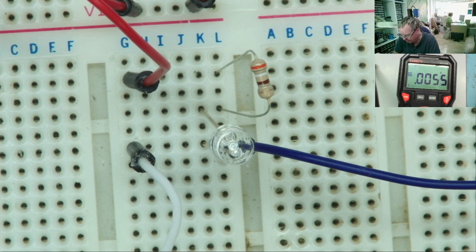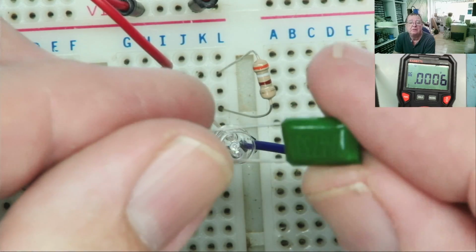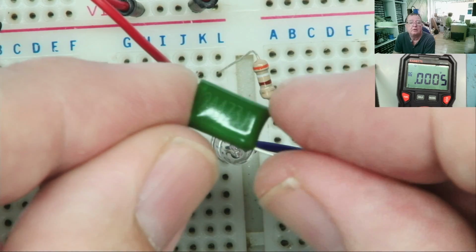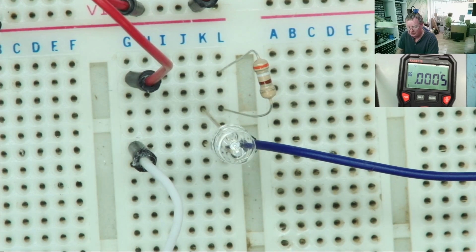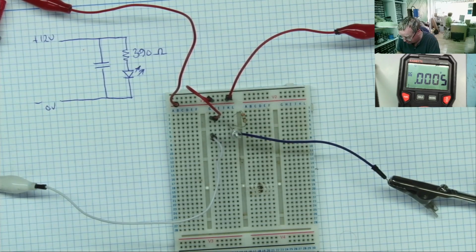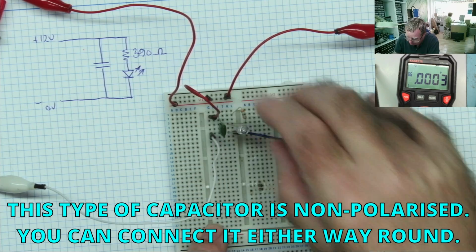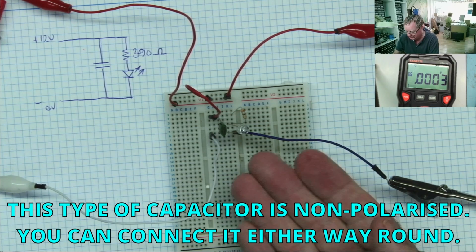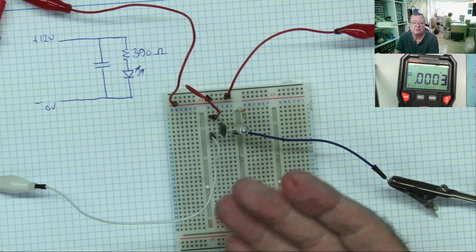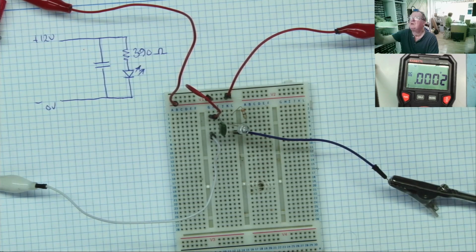If you watch part 1, you will know that capacitors store electricity in an electric field. So what happens if we add a capacitor to our circuit? Well, here's the 47 nanofarad capacitor. Okay, you can see there, 473. So we'll connect our capacitor exactly how we showed it in this circuit. So between the 12 volts and the ground, or 0 volts, from positive to negative. So what should happen now is this capacitor should charge up to 12 volts, and when we switch the power off, the LED should be able to run from the capacitor for a little while. So let's see what actually happens.